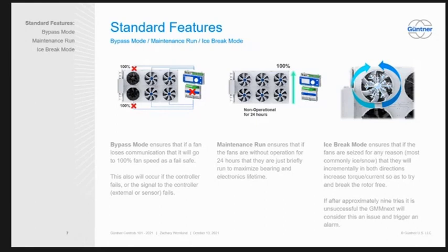When you load it up, the controller is going to ask how many fans are on this unit. You say 8 fans and 2 rows, and that's all you really need to do, plus some fan identifier information located on the electrical diagrams. It'll operate the exact same way as the 12-fan unit, but with 8 fans. And you can take that same configuration to a Costco site and load it on a 6-fan unit there.